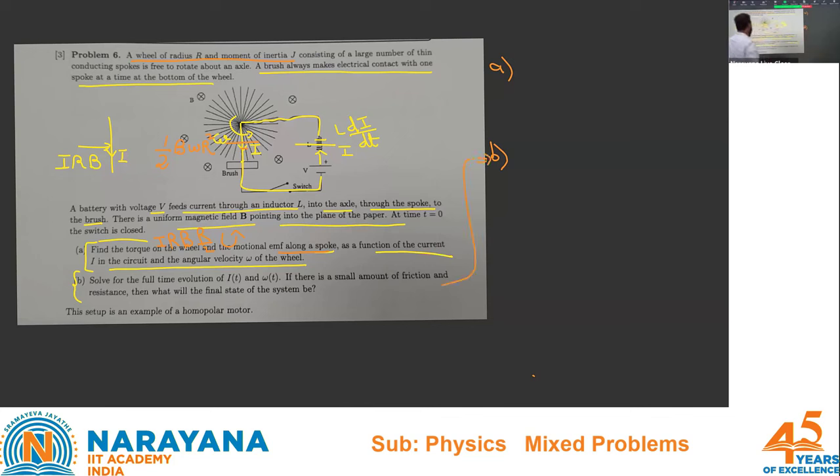What are the equations you are writing in the problem? So I will get a minus V term. I have got an L di/dt term. And then I have got that plus half B omega R squared term. And that will be equal to 0. That is my first equation.